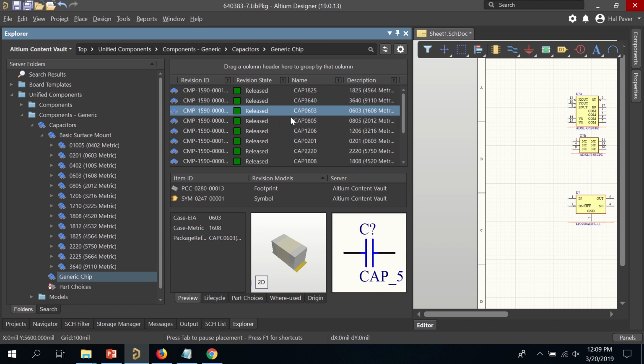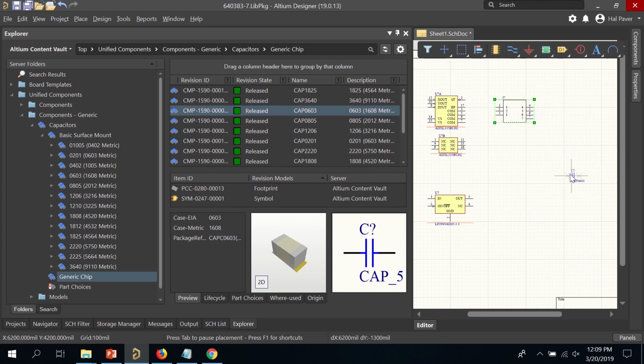So I'll right click, and I'll click place, and I'll move over in my schematic. And to rotate a component before you've placed it, you can press the space bar. And then keep clicking on the screen for as many capacitors as you plan to use. You can always copy and paste a component later or go back and add it from scratch.